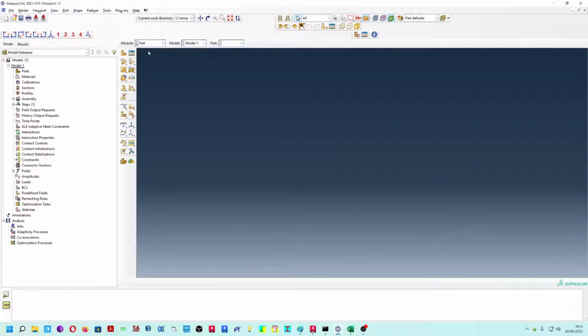Okay, so first things first. I'm not going to tell you anything about the main view, the commands. I would like to, as I said in the previous video, get the hands dirty and understand by trial and error. That could be long, but I assure you it could be definitely longer to learn first reading the Abaqus wiki, which is a mess, and then apply. We do begin with the part. The parts are the smallest item that is going to build our assembly, our structure.